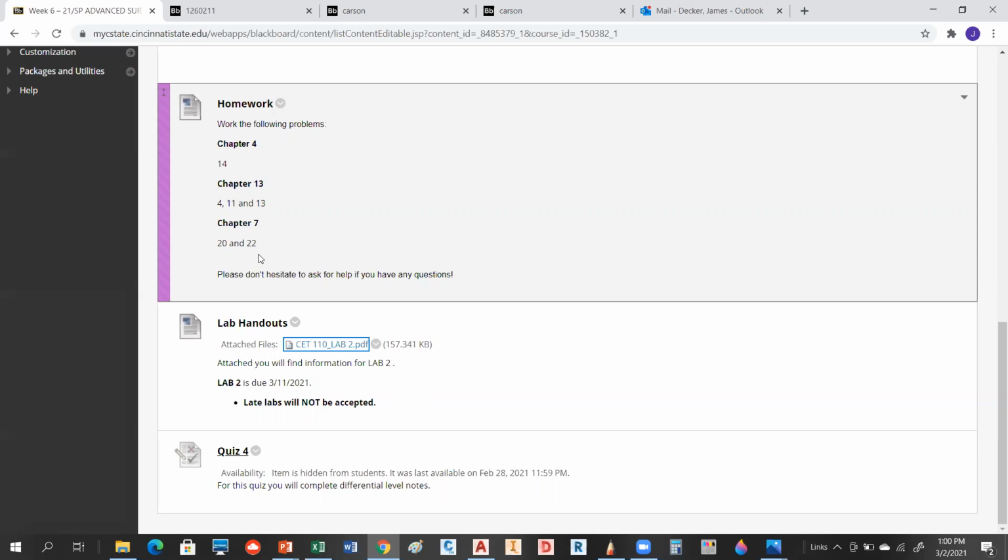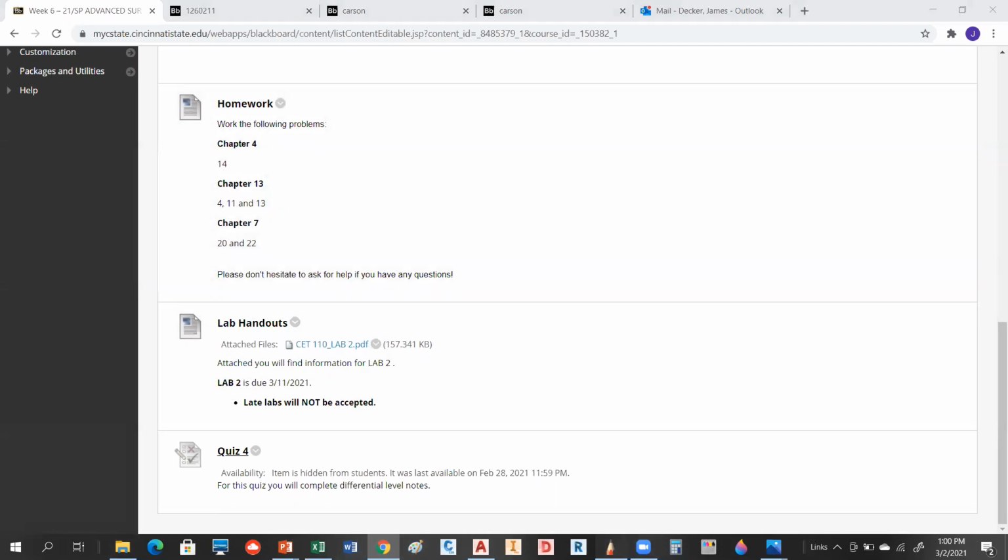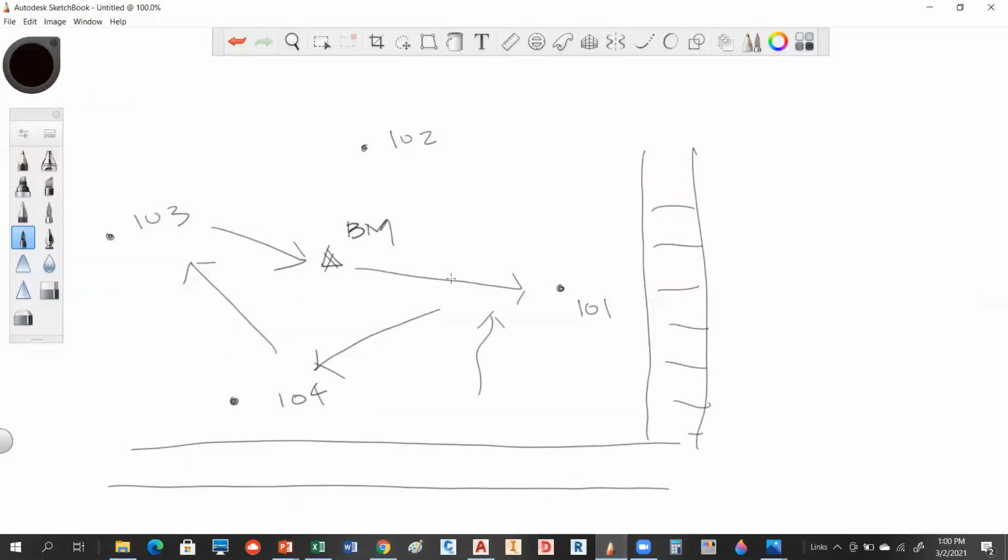But he says that you have a 100-foot long tape. It's laid on the ground that is sloping at 4%. So he wants to know what is the horizontal distance if the slope measurement is 300.23 feet. Okay, so what he's doing is he's saying, look, you're measuring a hypotenuse, and I want to know what is the horizontal distance. Okay, so let me draw a picture. When you do problems of a lot of these nature, any of that type, you usually want to draw a picture.